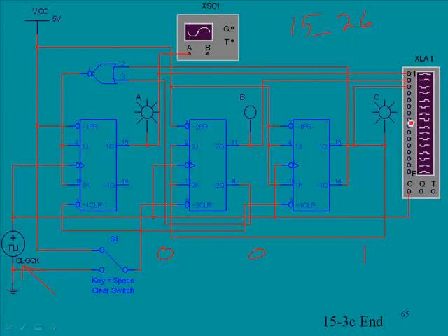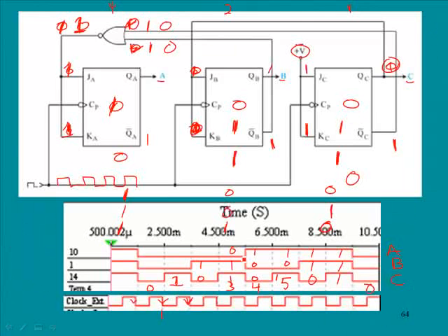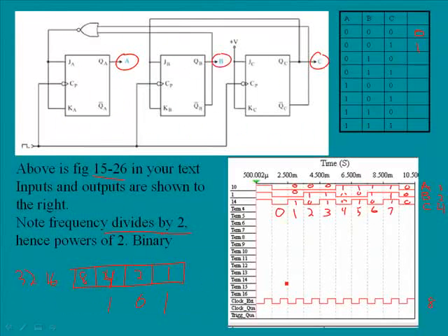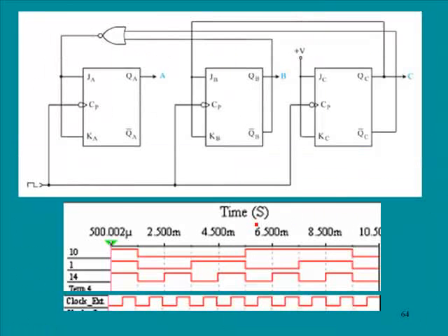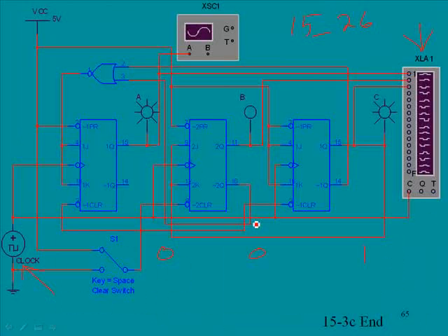Then this device over here, I'm going to just point to it. This is a logic analyzer, and in Electronics Workbench, if you click on that, that will give you this graph right here. It will show you the various outputs, and in fact, in your simulation, this third input is not in it. You'll need to draw a connection here going down to here, so you can see the actual output of the C flip-flop. Okay, that pretty much wraps up the theory of this.